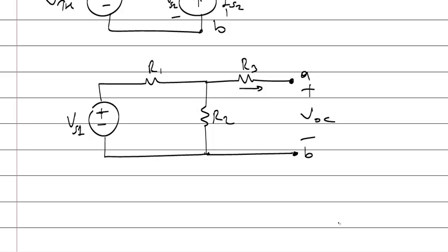Okay, what's the current on this resistor? 0, because there is no component connected. So the voltage of this point will be equal to A, because there is no current on the resistor. This point is equal to B, because they are connected with a cable. R3 doesn't have any effect on the circuit, okay, because it's an open circuit. There is a voltage. That voltage is divided on two resistors. There is a voltage division, and the voltage of R2, okay, this voltage is equal to the open circuit voltage, VAB.